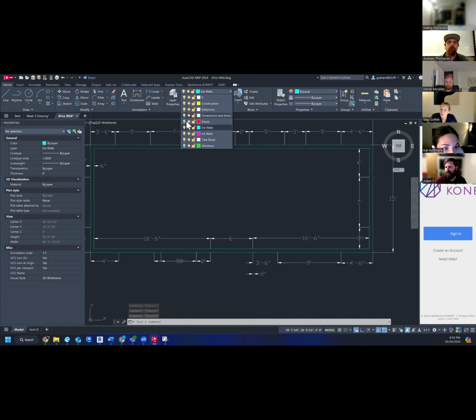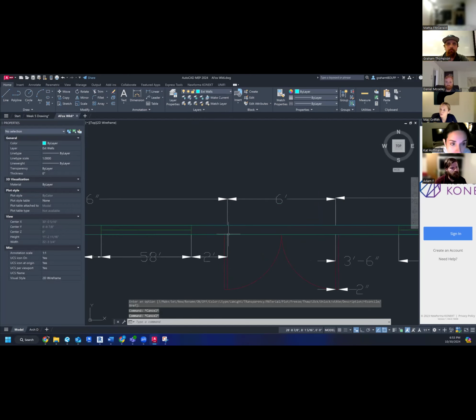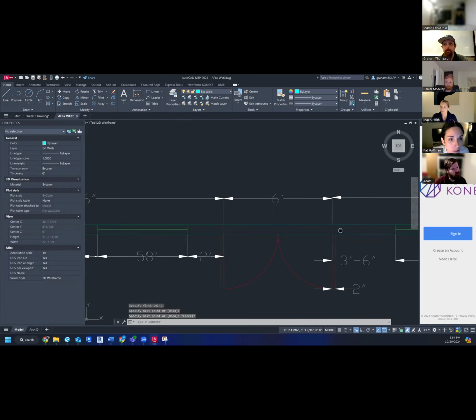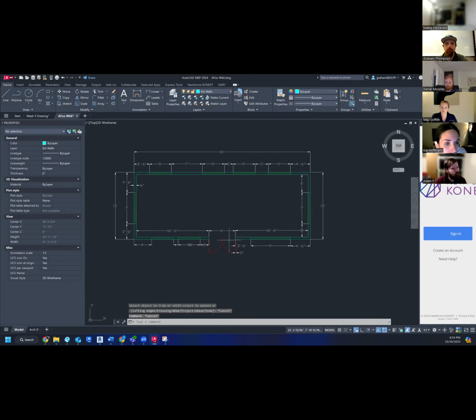Now we can turn this back on, right? Turn your doors and windows on. It looks like we still need to draw 2 lines. We need to draw this line, and then same thing here, because there's no way for us to make a jamb. And now we can trim this out. 1, 2, 3, and you've got everything built with a wall and windows, continuous line.